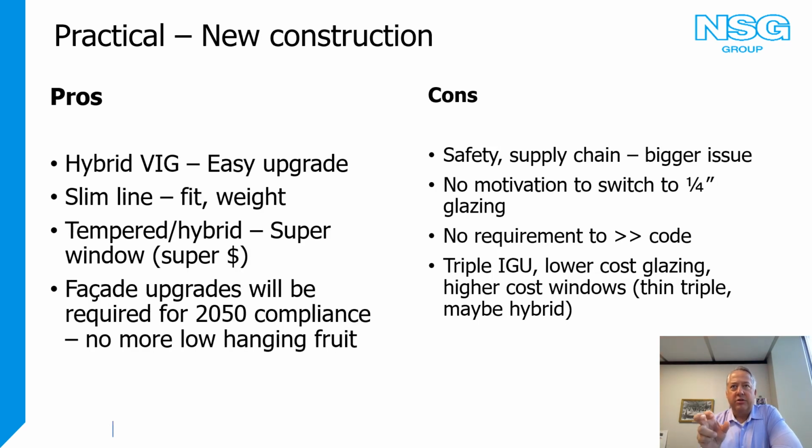And then these emerging technologies and carbon considerations. The way I think about this in terms of new construction is, a hybrid VIG is available today. There are people that make it, and it's a pretty simple plug and play. You take out your 3/4 inch IGU, you stick in a 3/4 inch hybrid VIG.